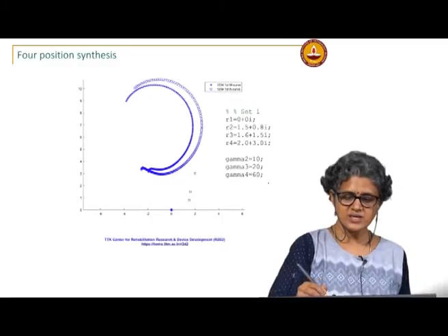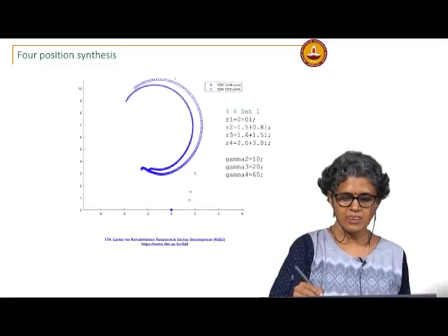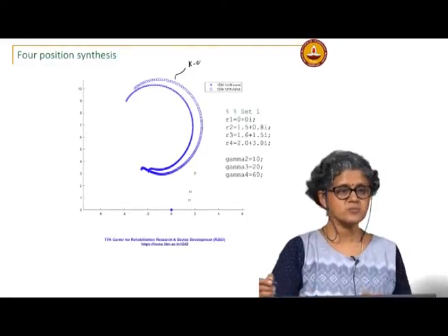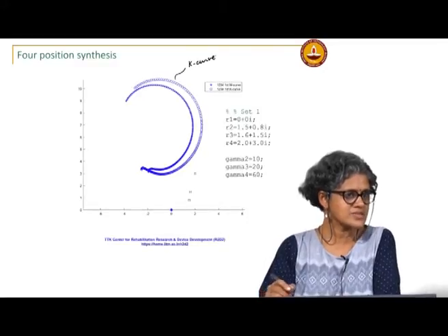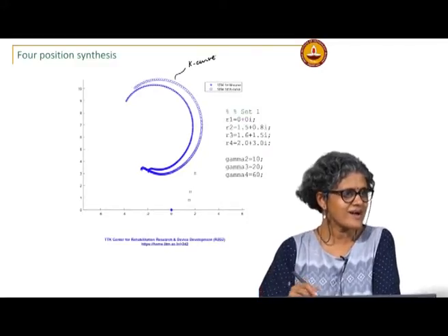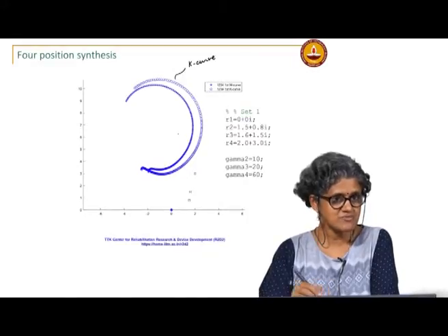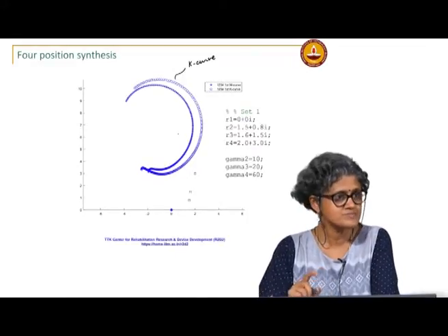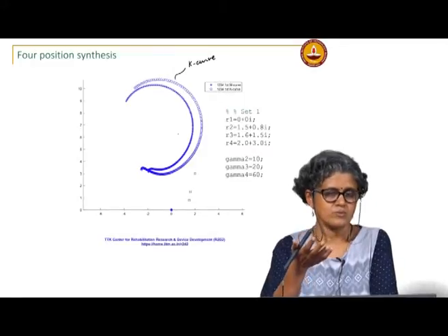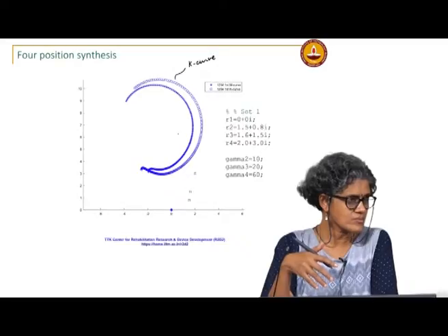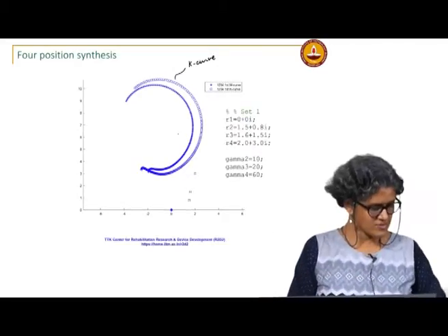This one with the circles is my K curve, that is my circle point curve, that is why I put circles so I would not forget. The other one with the stars is the locus of my fixed pivots. This is only for one mode of the compatibility linkage. Let me see if I have the other one.